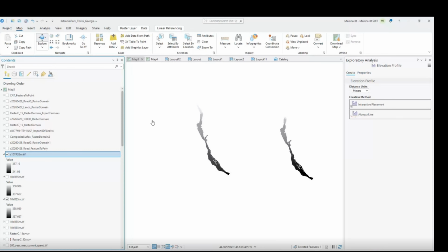If the projection is different, if the original file is different, then your scale, meaning the X, Y, Z coordinates, will be impacted. That is my concern, because sometimes when we project the files, it is projected in that coordinate only, X or Y, but elevation is impacted, or sometimes the Y coordinate, longitude, is impacted. So what is the solution if you are unaware of the projection, what type of projection they have utilized in the file, or to sort out the projection issue?